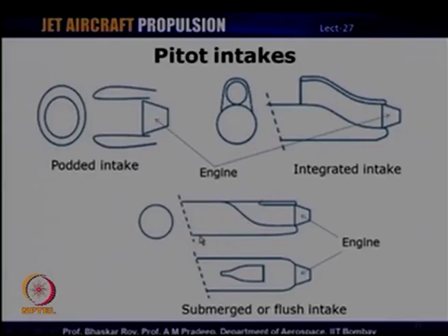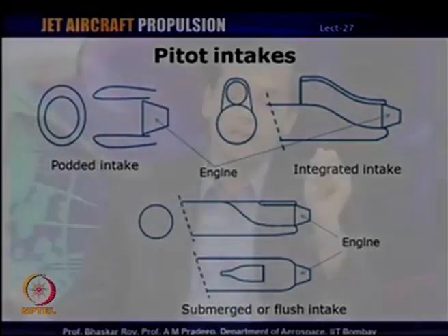Flush intakes or submerged intakes can ensure that this is possible, but of course there are performance penalties associated with this because of the very fact that the flow has to take a substantial curve before entering the engine. The performance of these intakes is usually very poor as compared to the podded intake or even compared to the integrated intake, and therefore that's the reason why they are used only under certain special circumstances, especially for missile applications and so on.